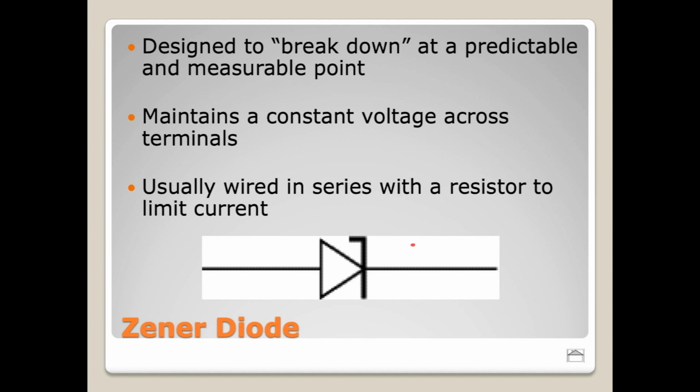But if that voltage is 32 volts, then that is above the 27 that was here, so that means it will allow it through. Okay, but what's interesting is because this is rated at 27 volts, what you will find on the back end is not 32, but 27.